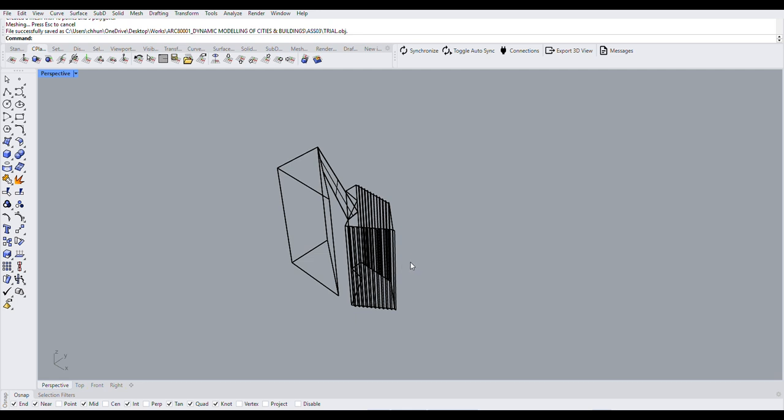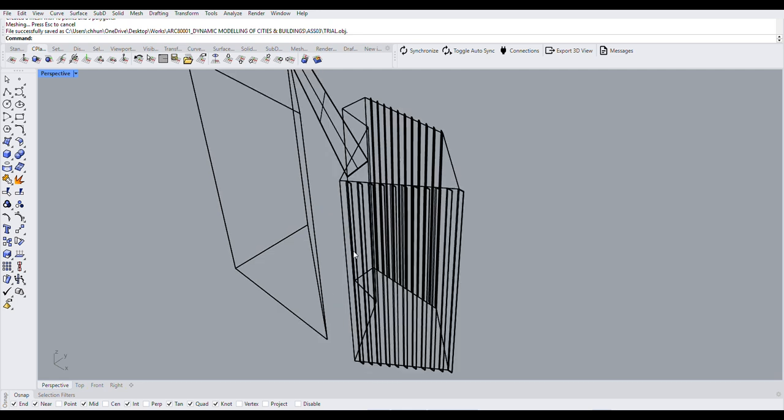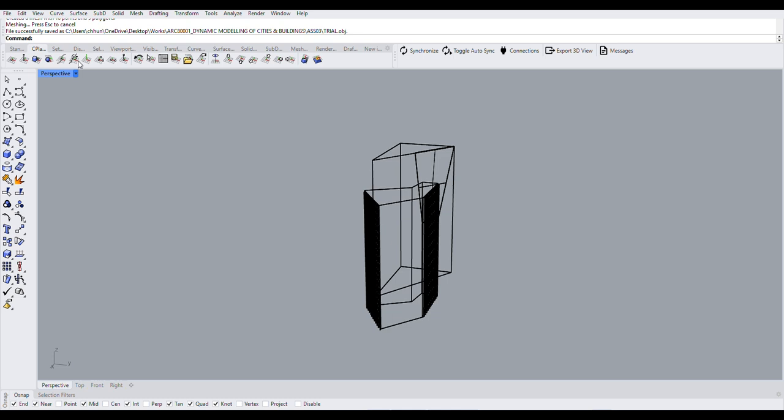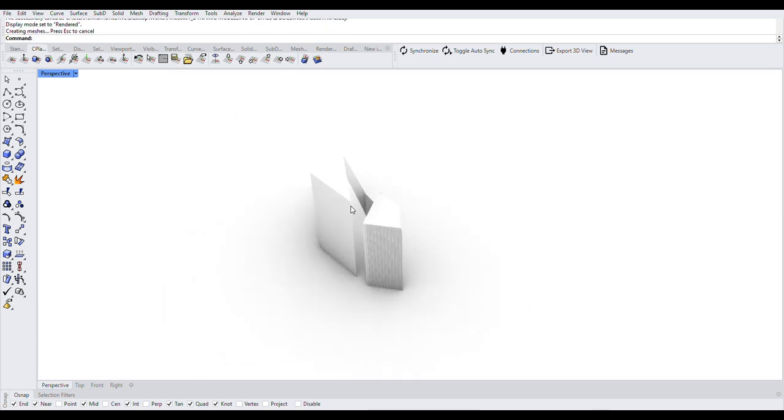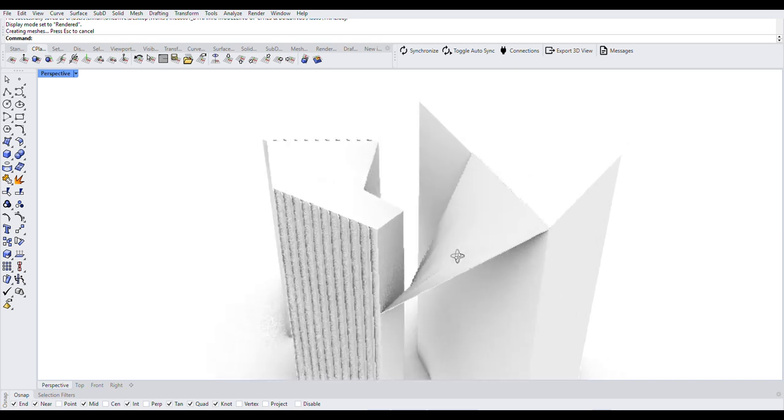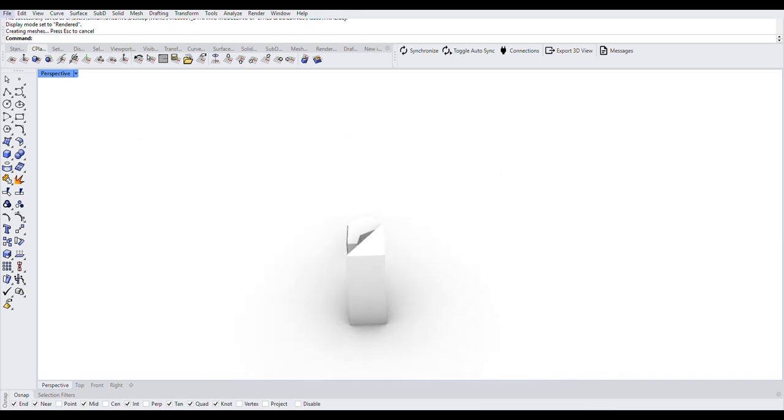Now you'd go into your model in Rhino. In this case, I have my model here as a proposal on the side of AMDC, scaled to how the site is within millimeters in Rhino. And what you want to do is to go into Files and click on Save As, and save the file as either DXF or the OBJ. I saved my file as an OBJ just to make it easier.